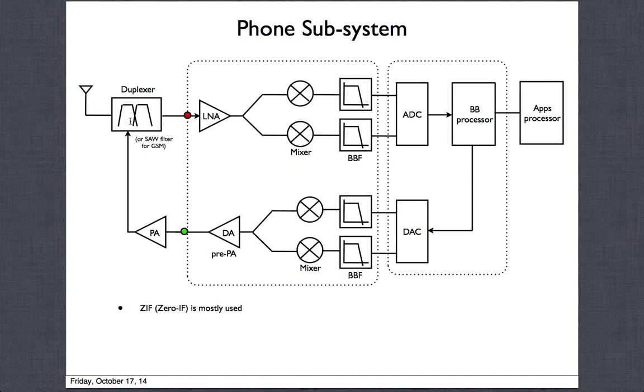So the bottom line is, the spacing may not be enough for this hardware to be able to distinguish the two. So when the TX transmits, we put a filter around it so the TX does not wash out the RX, and also does not put a lot of garbage outside into other bands. That is the need for the TX filter. We are only transmitting in the band, and the rest of it we are trying to filter out to save our own RX, as well as to stop pumping garbage noise into the other guys in the adjacent bands.